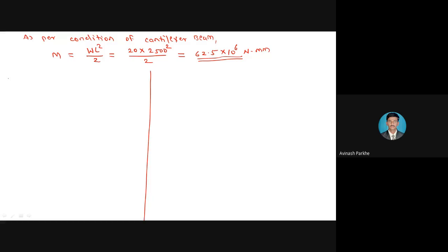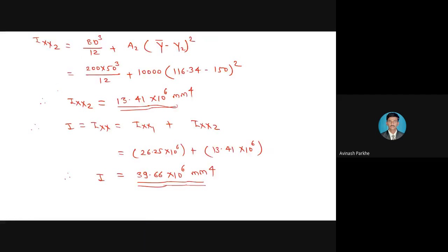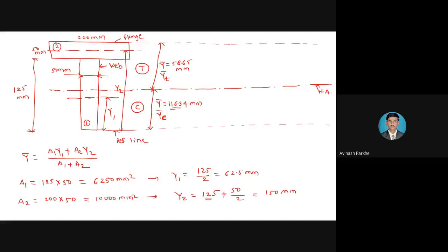Now we have to calculate the bending stresses. First, the stress due to y bar, where y is equal to yt. So what is the yt? What is the value of yt above the neutral axis?